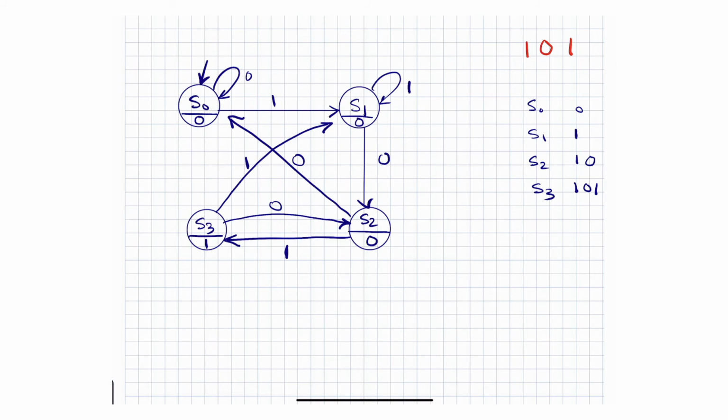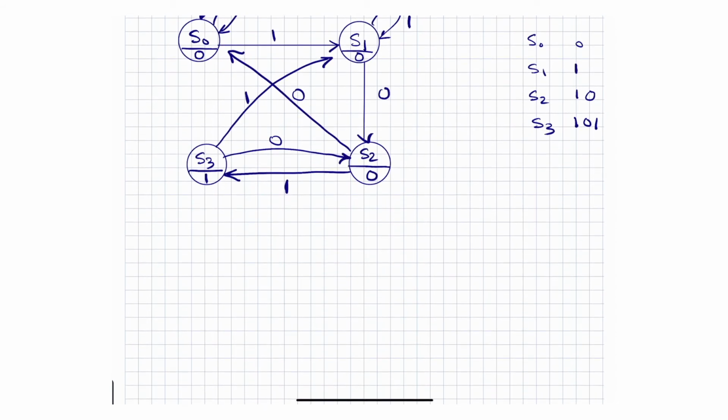So now the next step is to code these with some sort of binary code. Again, I can use 4 flip-flops, 1 flip-flop for each state with one-hot encoding, or binary encoding. I'm just going to do binary encoding for that particular case. Of course, you can do state reduction, but I'm just not going to do it. So with the binary encoding, let me just fill in that table.